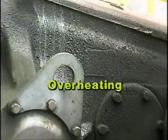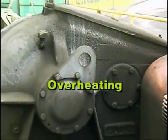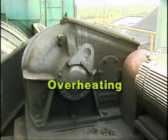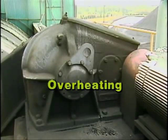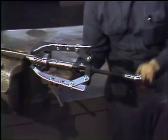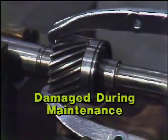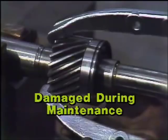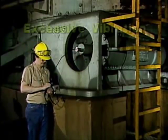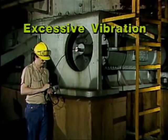Another common cause of bearing failure is gear unit overheating. This condition could be caused by a number of things. For example, overheating could be caused by a buildup of dirt on a gear unit that is cooled by radiating heat to the environment. A third reason for bearing failure could be that the unit was damaged when it was first installed or during subsequent maintenance. Another cause for failure could be that the unit experiences excessive vibration when it operates.